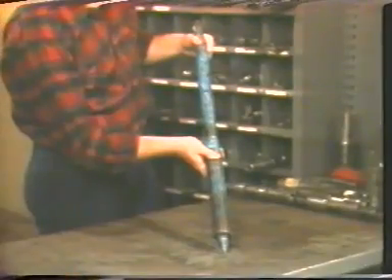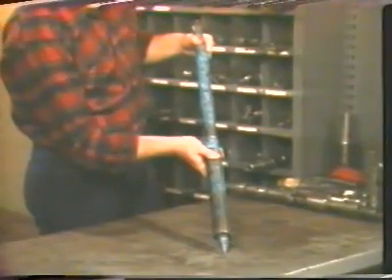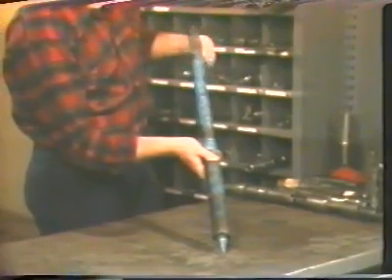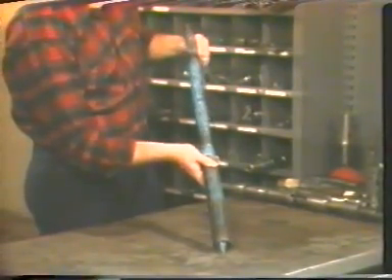Some tools are designed to both locate and retrieve the wire line during one trip in the well. These tools are called wire retrievers. The oldest and most popular of the wire retrievers consists of a mandrel, which has a spear point on the bottom and a slotted skirt which floats over the mandrel. The ID of the skirt and the OD of the mandrel are machined to have matching tapers, which, when the skirt moves down over the mandrel, will wedge the wire line between them and grab the wire.